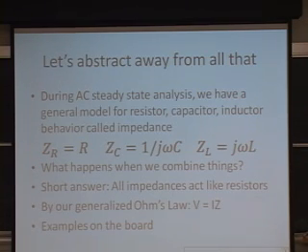Okay, so the important thing to note about impedances, at least in the context of this kind of circuit, is that we have a resistance R. So the real part is R. Generally, that's always positive. Then the imaginary part we call the reactance. So normally we would write this as R plus jX, and X is called the reactance. Positive reactance means the circuit behaves inductively, and a negative one means the circuit behaves capacitively.